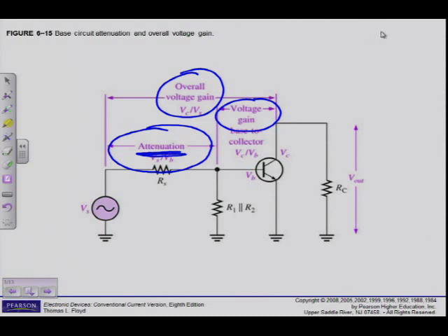Remember when we talked about the AC analysis of the amplifier in the previous lesson, we had to simplify the circuit. Firstly we had to take our amplifier circuit and draw the AC equivalent circuit. Remember, because of the way the capacitors act and the DC supply, all of them acted as shorts. Can you recall? Alright. So then I simplified the circuit and I saw, as I can see in this figure as well, that R1 is in parallel with R2.